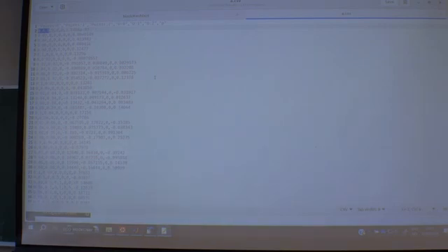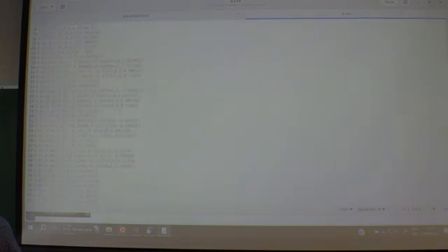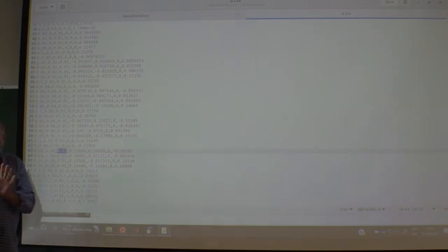You can get the idea if you look at, say, the set positions here. Here they are 0, 0, 0, 0 all the way. But if you look at the bottom of the file, you get the exact same numbers, but now Z equals 0.01, meaning he gives you 2 different fields, but they are identical. One for set position 0 and one for set position 0.01. So you sort of have twice as much information here. Well, you only need one of them.